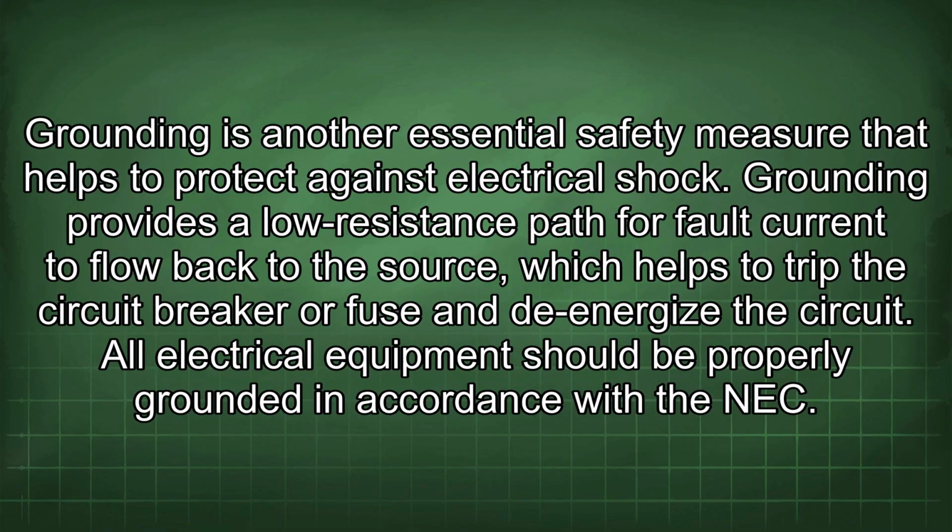Grounding is another essential safety measure that helps to protect against electrical shock. Grounding provides a low-resistance path for fault current to flow back to the source, which helps to trip the circuit breaker or fuse and de-energize the circuit. All electrical equipment should be properly grounded in accordance with the NEC.